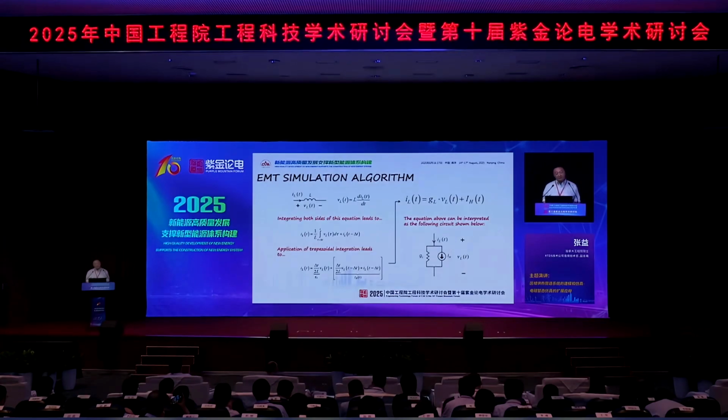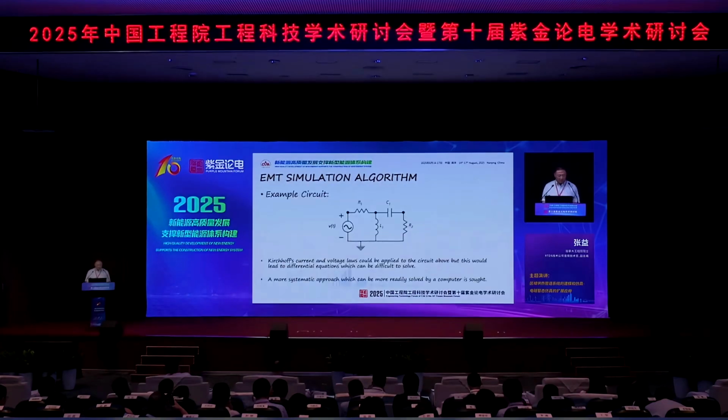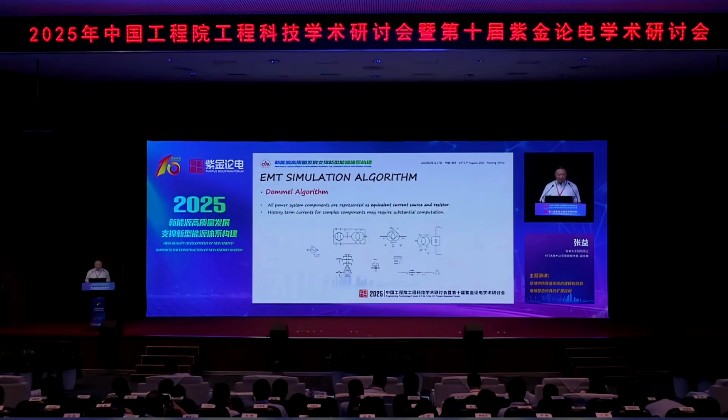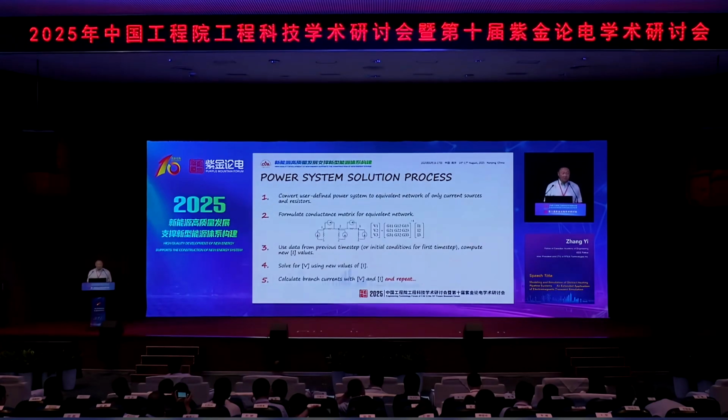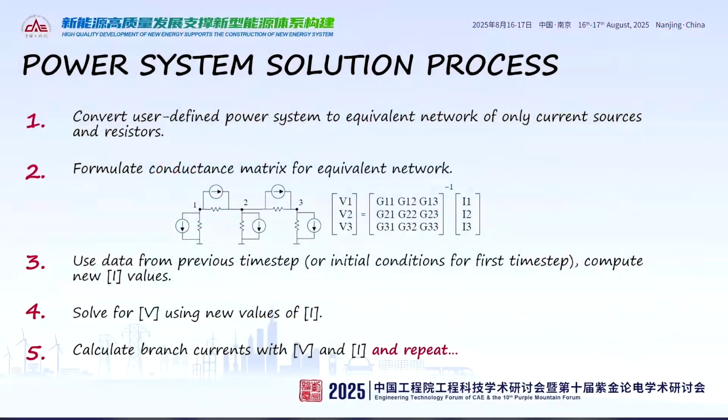If every component has this format, then we can solve the differential equations in the form of algebraic equations. This reduces the problem by one layer, so you can solve the dynamics using linear equations. Basically, it's nodal analysis. If, for example, for the transformer, valve group or transmission line, we can write out all these equations, then we can solve it very easily using nodal analysis, which we were taught well in the second year of university.